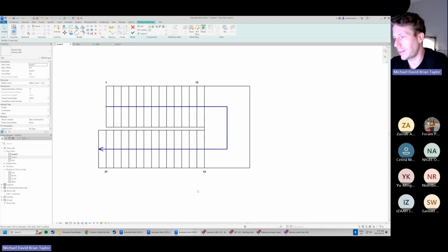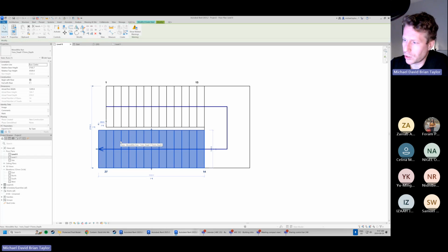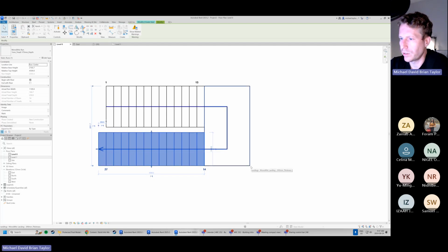And as a second way to set these, my preferred option is typically to click on our run, so our first run here, or excuse me, that's our second run. We'll click here and we can actually just, much like our dimension tool, modify this and type in here 1100, hit enter. We should see it just shrink a little bit.